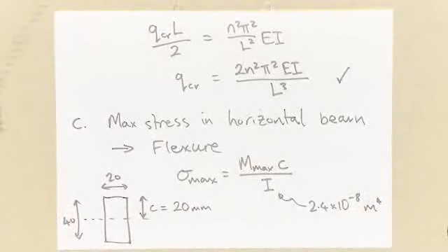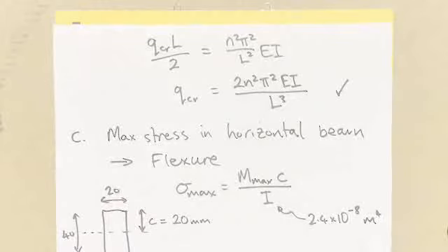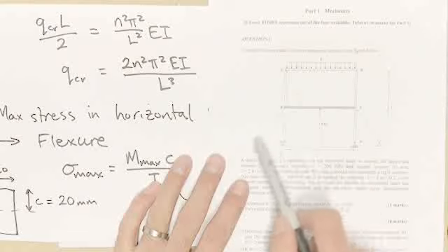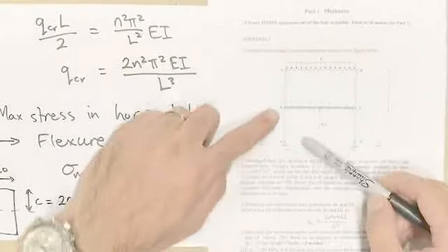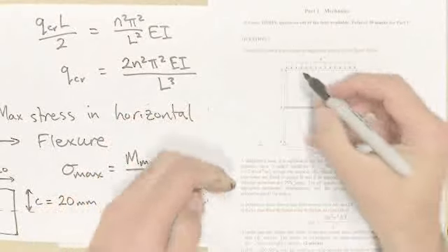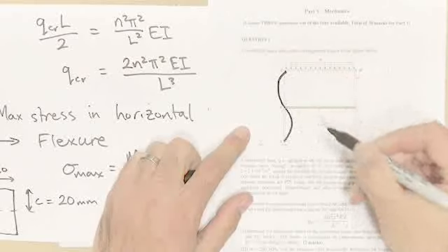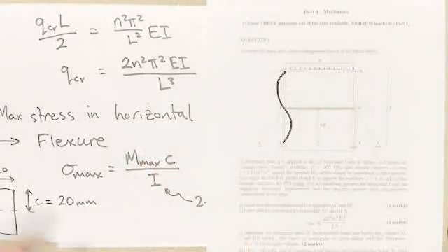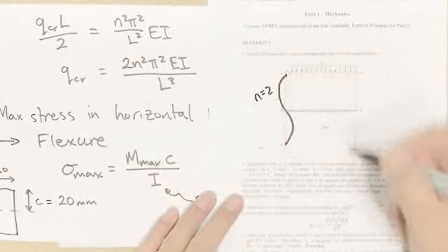Recall that this question has these strange guy wires and rigid beam, which I said was stopping B and E from moving, which means this is a column that is supported in the center, which means it's going to buckle like this. And that, you should all be realizing, is mode 2 buckling.